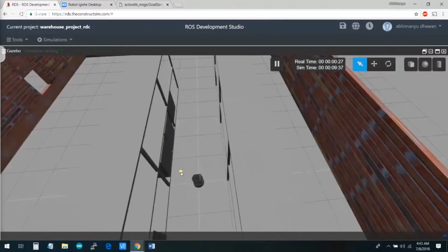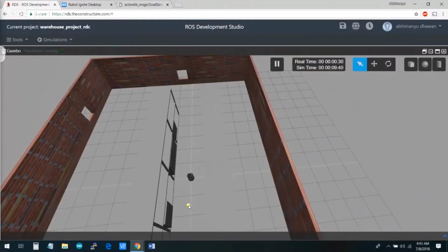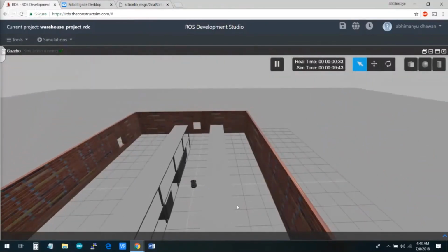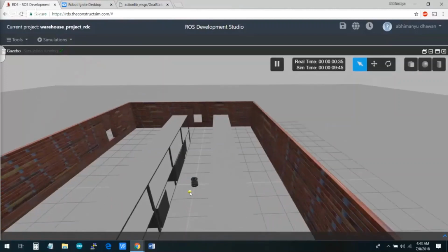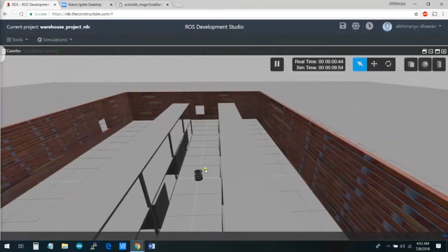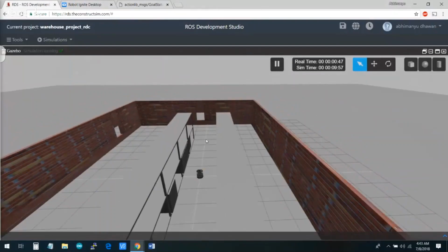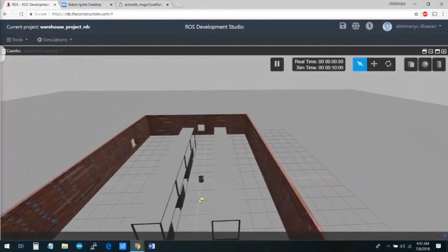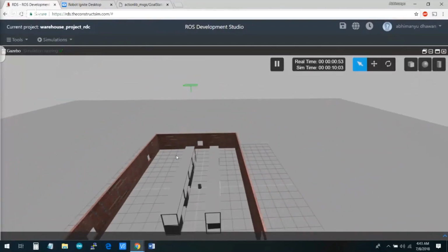So here you can see that there are two shelves, right? Just two shelves. And this area is empty, this area is empty. So we don't want the robot to do the scanning when it is in this area or in this area. It just scans when it is between these two shelves. So basically, extremes mean that we are providing it an end boundary that between these 2 points only you do the scanning, and if you are not in between these 2 points, you don't do any scanning. You just follow the waypoints back to the actual shelf area. So that's what extreme means here.